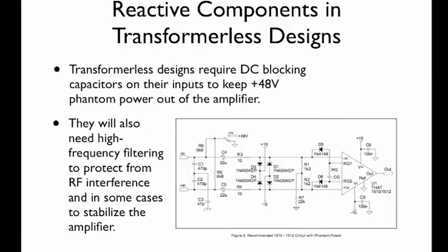This circuit also intentionally filters low frequencies because we need to be able to set 48 volts phantom power at the input here. So we have a high-pass filter which is formed from this capacitor with a resistor to ground here. Again, it's a frequency-dependent voltage divider which forms a filter in such a way that we have a high-pass filter.